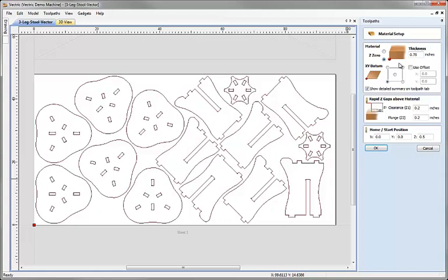Whereas if I set from the top of the material and assume that my material is a constant thickness, but I had some areas that were a little bit thicker, then there would be some parts where I hadn't cut all the way through. This is a completely personal preference, and you should always choose whichever you're most comfortable with to work. In this case, we'll choose going off the table because it'll give us an opportunity to show how that type of setup could be used within the software.